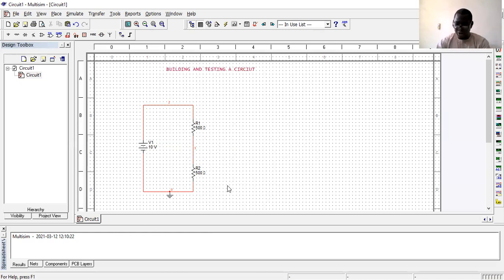So I can now put the instrument or the indicator. I've done arranging the circuit element. So follow the manual, you see the first step, place the component on the circuit window. The second step is arranging the circuit element, then wire, step number 3, wire the component together. Then step number 4, set values for the component, which I've already done, I've combined together. Then save your circuit, very, very important.